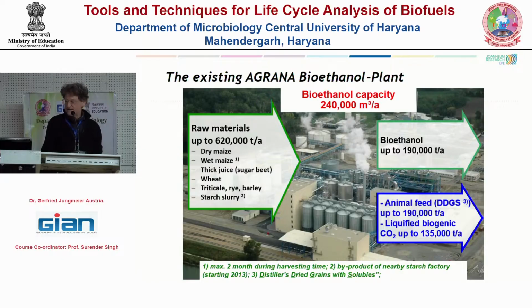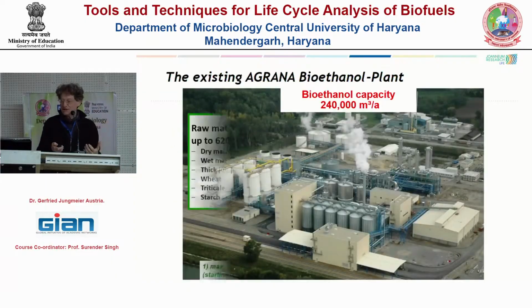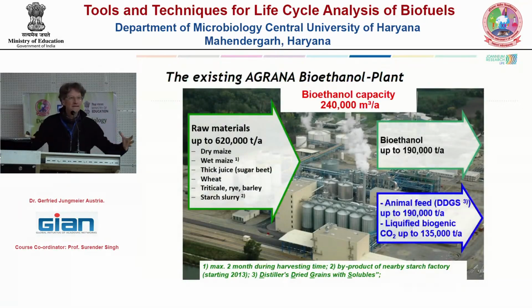Yeah? And the collection of the CO2 is also part of this formula, because of this term here, emission saving from carbon capture and replacement. So if you really collect the CO2, you also get a credit in that formula. Yeah? Because on one hand, you need additional energy to collect it and to compress it, but at least you get a credit, because you're really also substituting fossil energy.